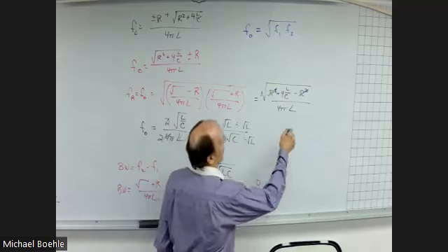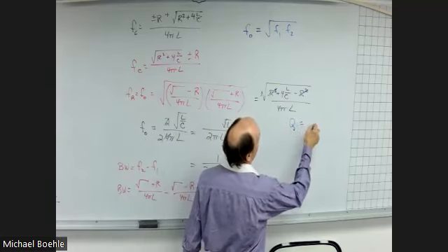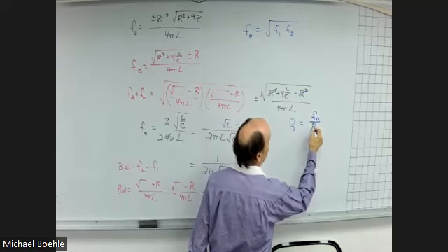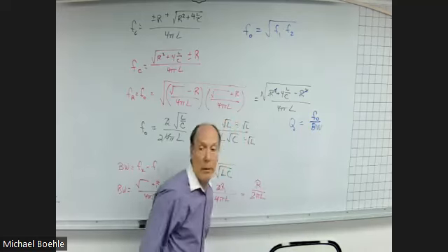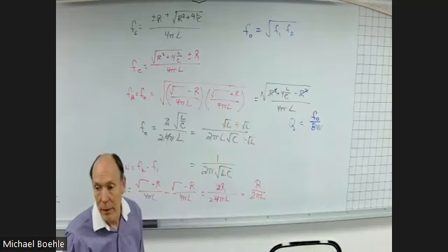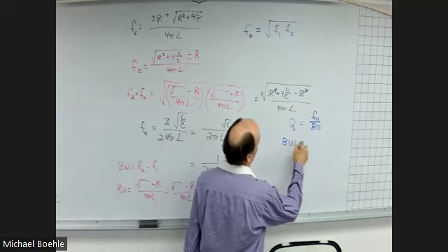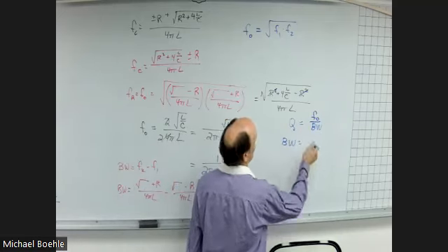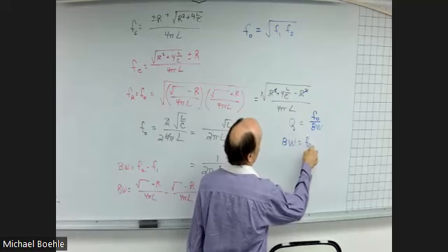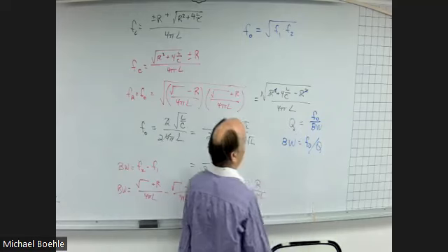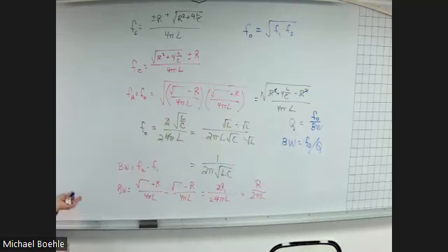We do have the fact that Q is equal to the resonant frequency divided by the bandwidth. Which means the bandwidth is equal to the resonant frequency divided by Q. Divide both sides by Q, or multiply both sides by the bandwidth. We just swap that relationship.